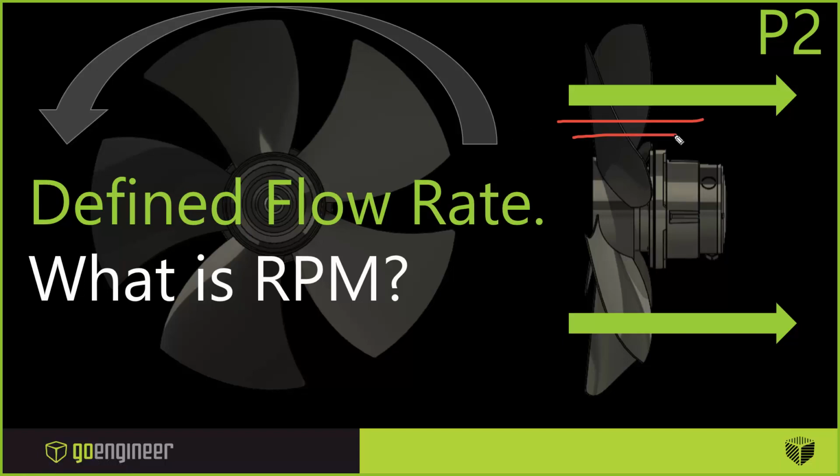And in reality, the fluid pressure, or torque on the blades, causes the fan to begin spinning. But in flow simulation, I can't have that fluid structure interaction, so instead, I'm going to measure the torque on the blades, and adjust the RPM until the torque is approximately 0. Very similar setup, just different kinds of optimization that we're doing.